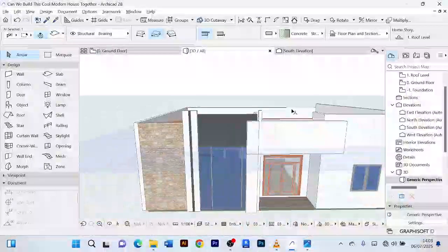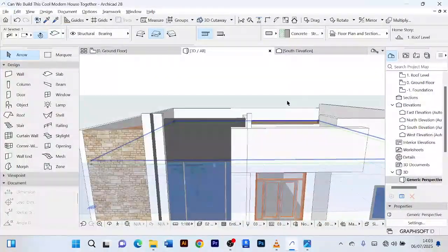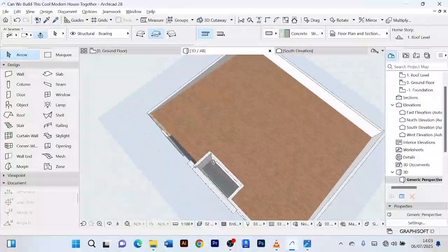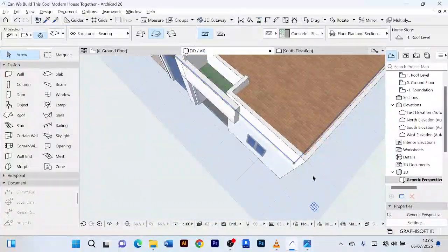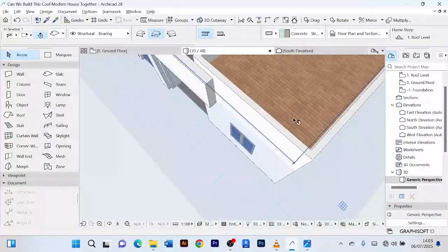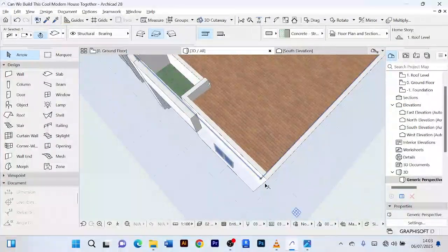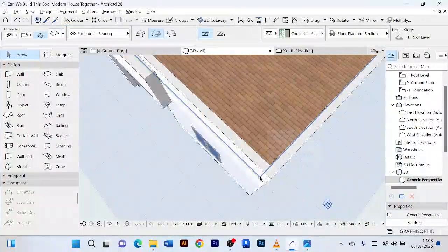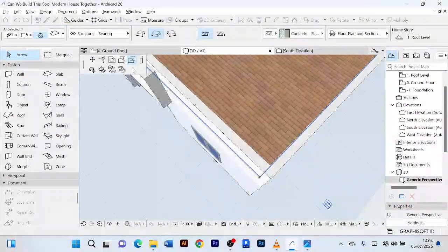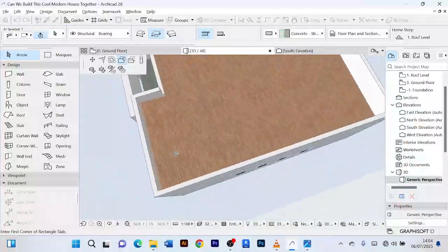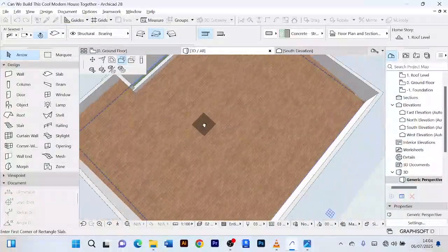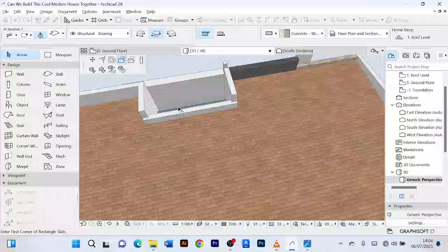And I think the best way is to do it from here. When you try to click on this, you see after selecting the floor or the slab, you can click on this node, this black node, then you come to addition instead of subtraction. You click add, then of course you make sure you are properly seeing what you are doing.